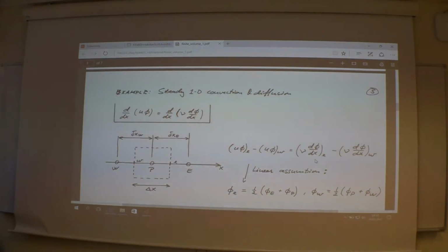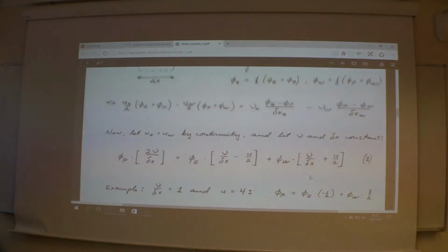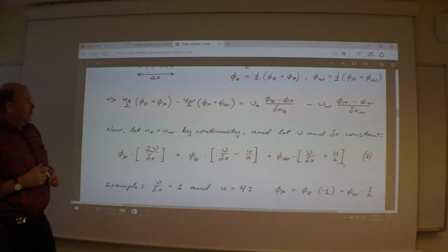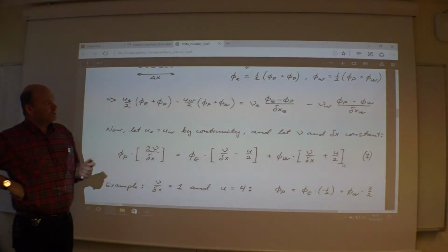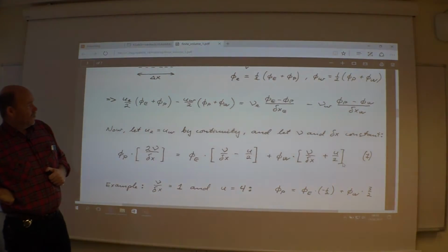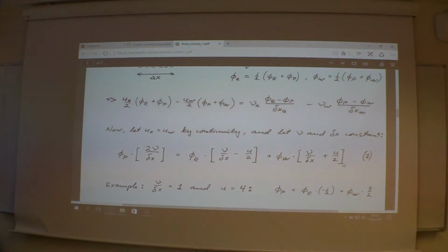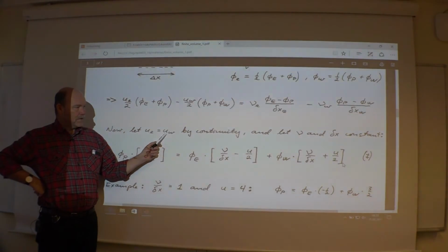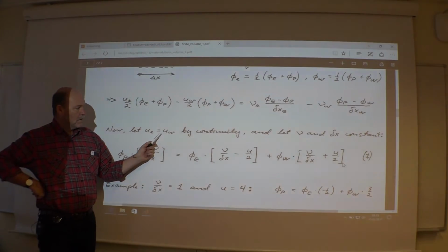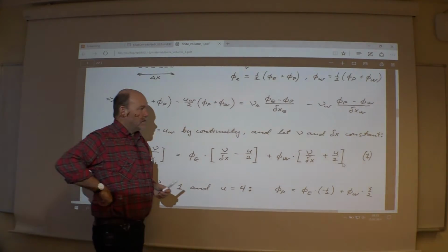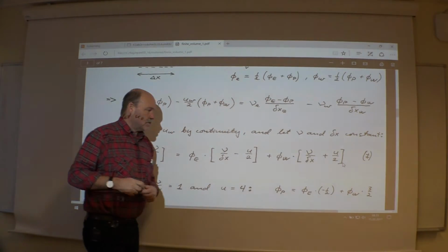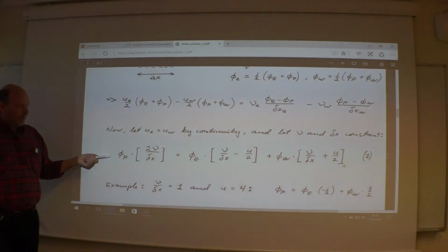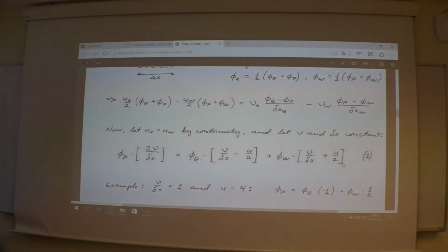Now we run into problems if we try to solve this directly using linear interpolation as such. Your equation system here. So no problem so far. And then we make it a very easy example. Let the velocity be constant. I mean, this one is given, it's not the unknown in the problem anyway. And of course, let the viscosity be constant, and also the mesh be uniform. The equation system will be reduced to something like this. So this is the classical example that Patankar uses.